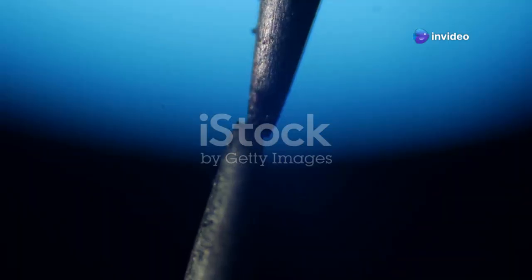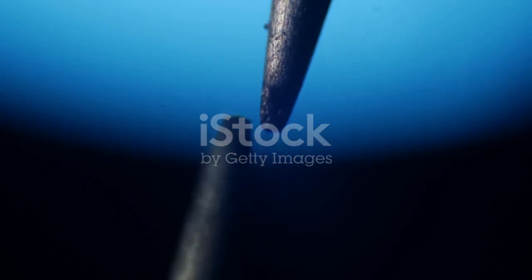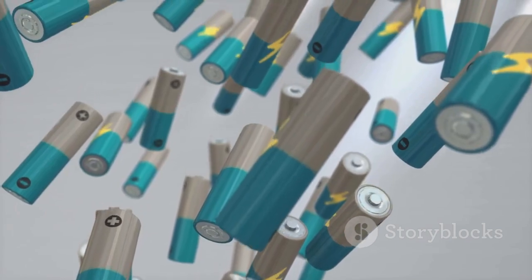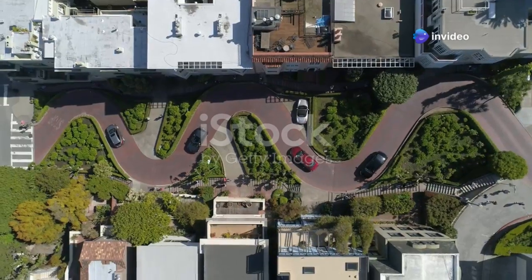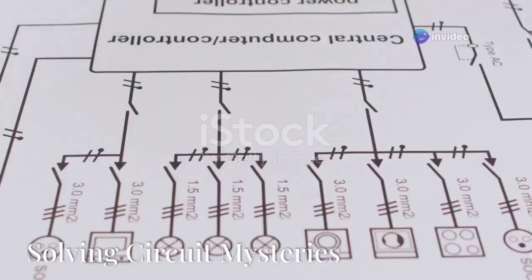KVL states that the sum of all the voltages around any closed loop in a circuit must equal zero. This means that the energy supplied by the source is used up by all the components in the loop. It's like taking a round trip back home. You might go up and down hills along the way, but you always end up back where you started.